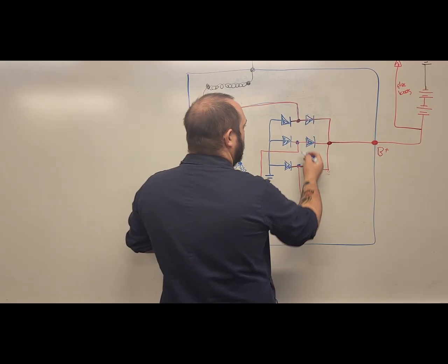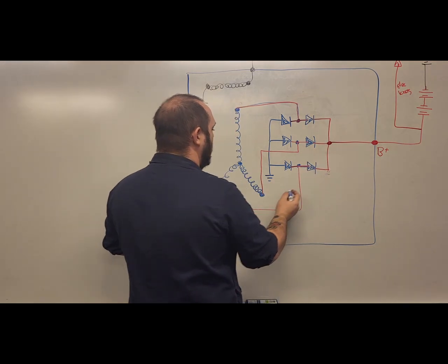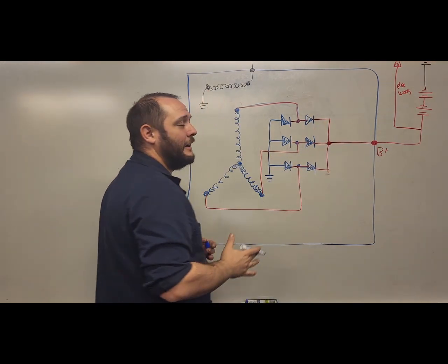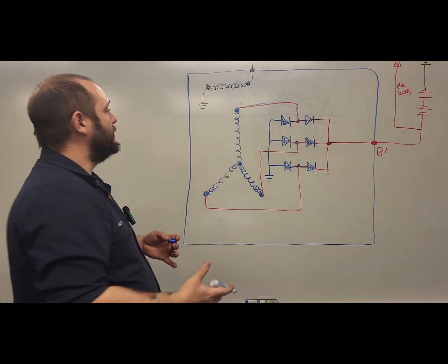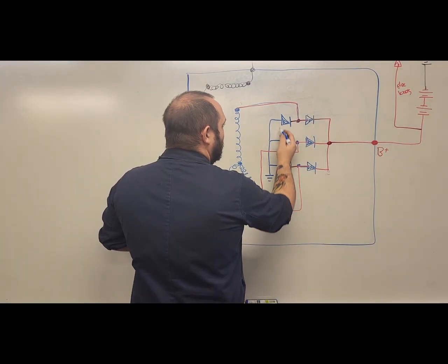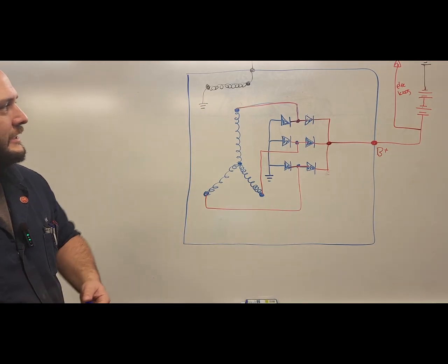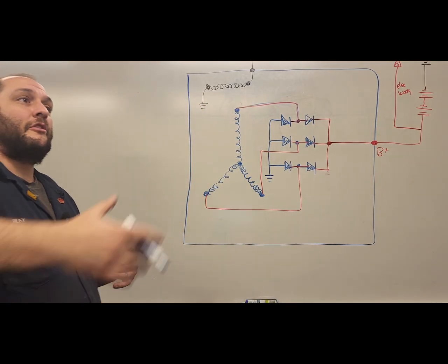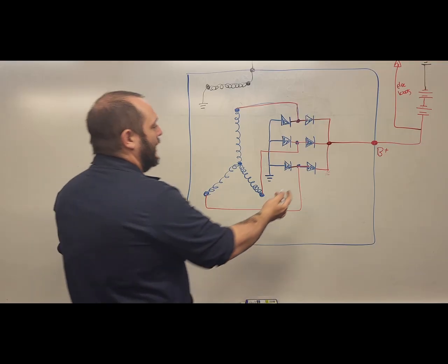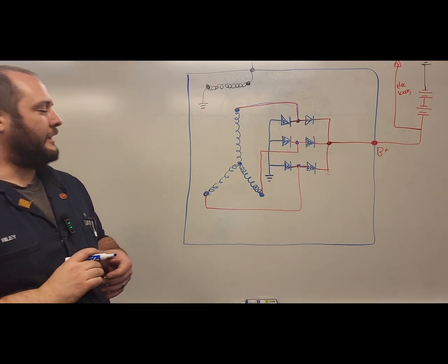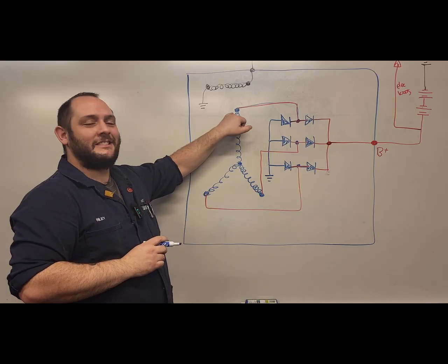We've got our positive diodes, allowing the current from our stator outputs to go out to our battery and to run our electrical loads. Conversely, we have our 3 negatives, or the return path. That puts those 3 diodes in the forward bias to the return, or the ground, and my 3 positive diodes will be in the forward bias for my output, the current induced in my stator.